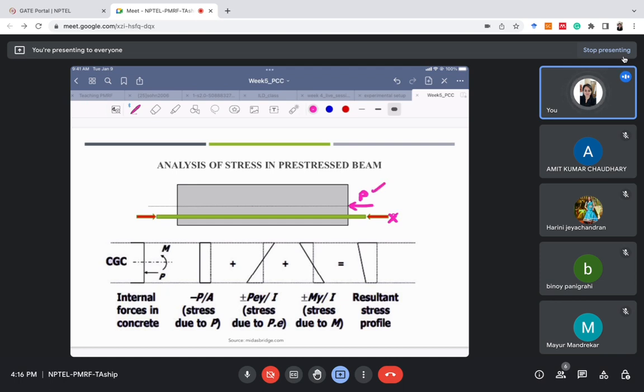The direction of the moment should be, I'll draw, first I'll draw, so this is the moment. The arrow of this moment will be in the same direction from where we have shifted the load. Here we have shifted the load from the bottom, so the direction of the arrow is downward here. And what is the value of this moment? The value of this moment will be P into E. This shifting I'm doing only for the simplification of the analysis.